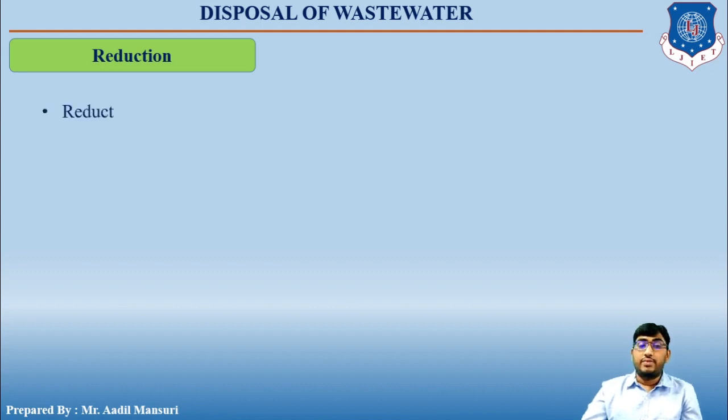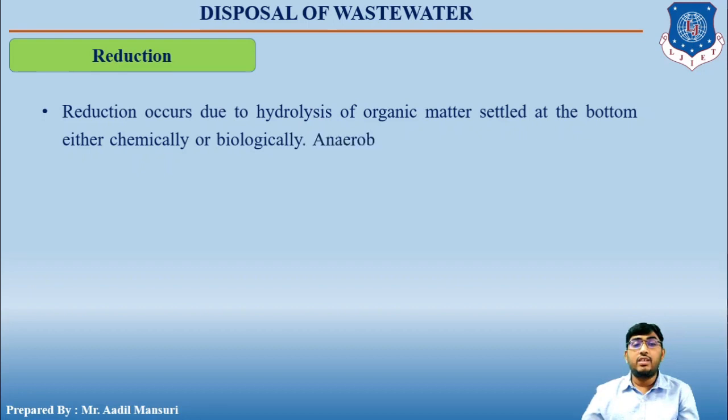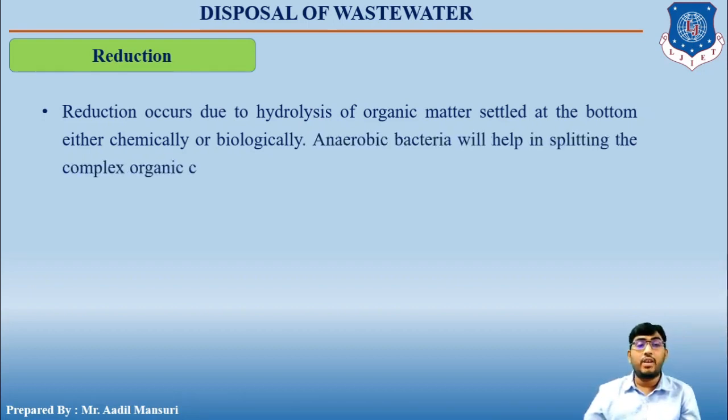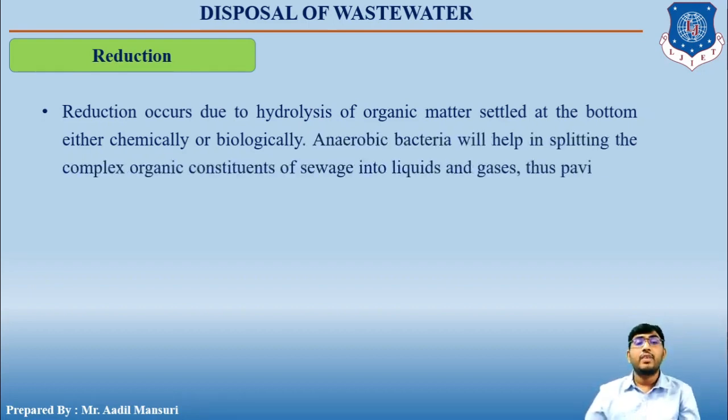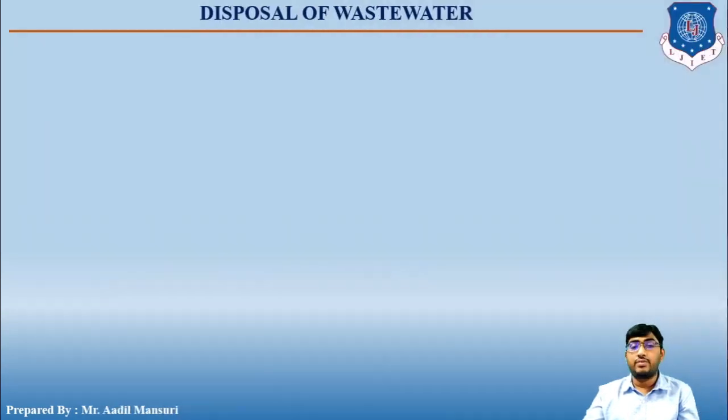Next is reduction. Reduction occurs due to hydrolysis of organic matter settled at the bottom, either chemically or biologically. Anaerobic bacteria will help in splitting the complex organic constituents of sewage into liquids and gases, thus paving the way for their ultimate stabilization by oxidation. So these were the different actions which take place in self purification.